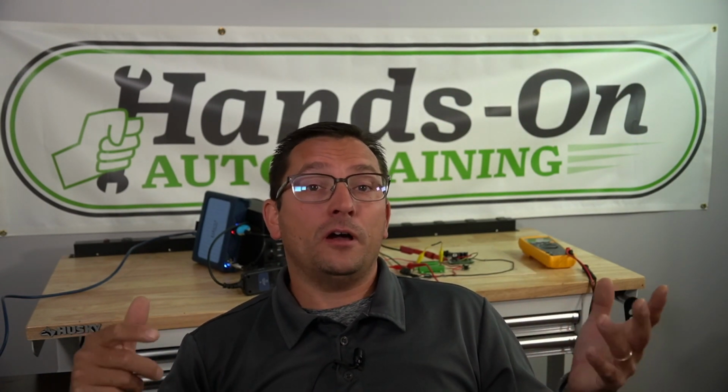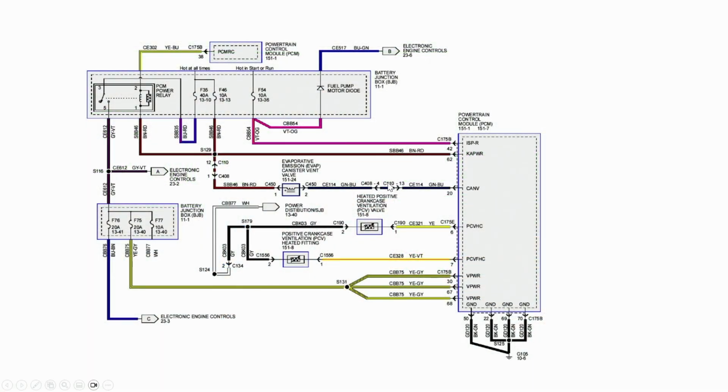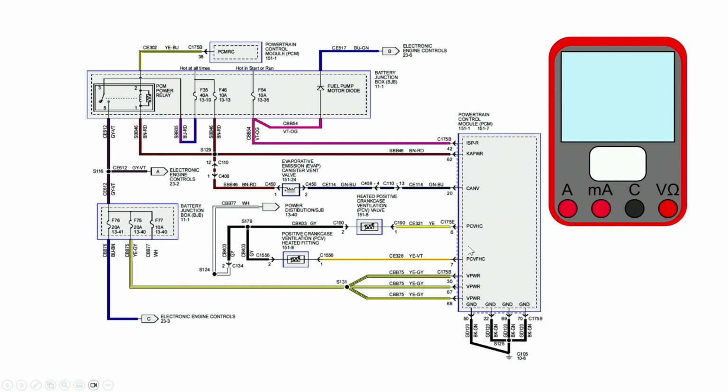I was about 50 minutes into this thing. I'm like, that's it. I'm checking powers and grounds. So here we go. We've got ourselves our diagram. This is a diagram from AllData, alldata.com, just so you know. I want to take my multimeter and check for power. I'm going to go ahead and ground my multimeter. Always go to battery negative. On this Ford, that was very easy because the battery's right up front. And I go to my ground.